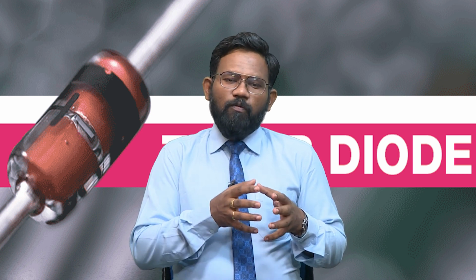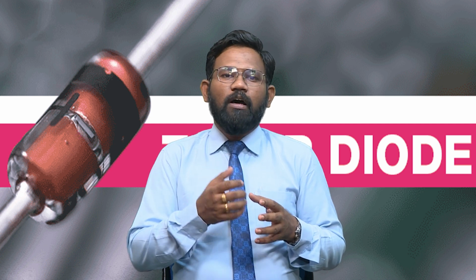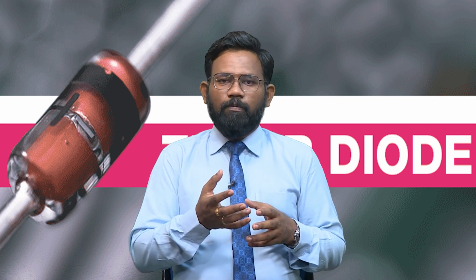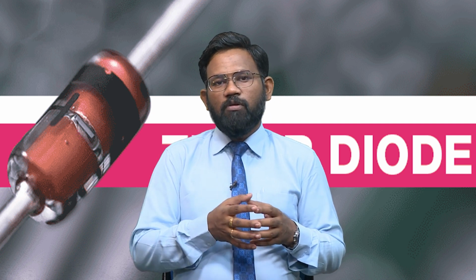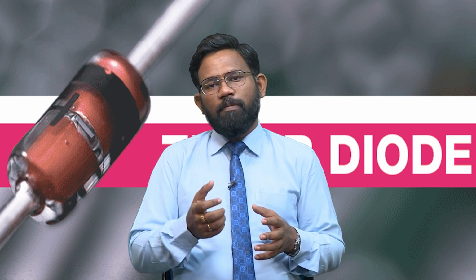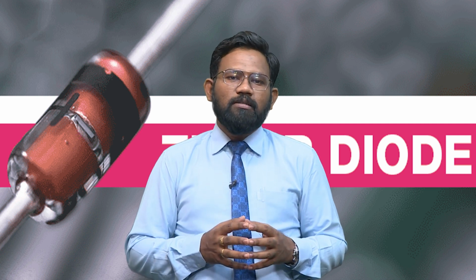So if we want to obtain the breakdown before the avalanche breakdown, the doping should be increased. That means that in a PN junction diode, when it is made heavily doped, that breakdown can be obtained before the avalanche breakdown, and this is the working principle for the Zener diode.